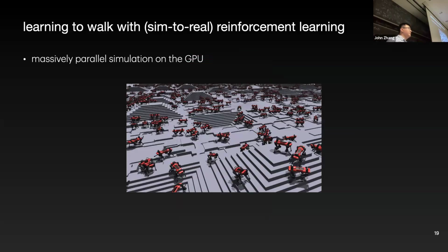In particular, there have been lots of off-the-shelf GPU accelerated simulators. You don't need that big of a GPU to get thousands of robots simulating in parallel. Most of the standard ones, Isaac Gym, there's a new simulator coming out every other day, but Isaac, MuJoCo, all that stuff parallelizes extremely well on standard desktop or even laptop GPUs.